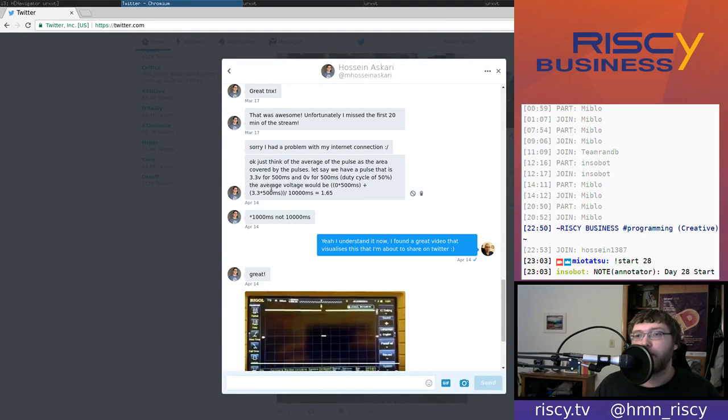Okay, so Hossein says, just think of the average of the pulse as the area covered by the pulses. So say we have a pulse that is 3.3 volts for 500 milliseconds and 0 volts for 500 milliseconds, a duty cycle of 50%.